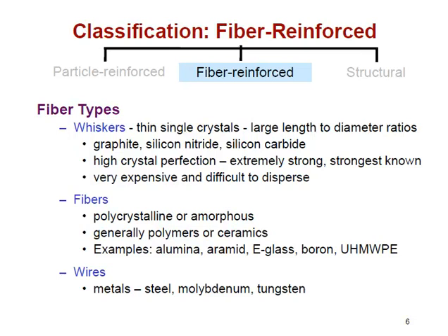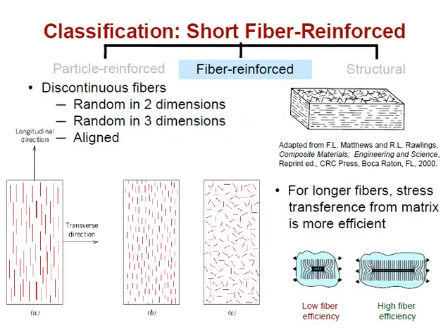This is definitely the case for the ultra-high molecular weight, high modulus polyethylene fibers, and also for most carbon fibers. Obviously, in the case of ceramics, we can get polycrystalline. We're not going to have chain alignment since they're networks, and they will, though, get their strength from the fact that they are covalently bonded, and the fact that, despite the fact that they are ceramics, because they are so thin, they are in plane stress, so that defeats some of the fracture toughness limitations. Metal wires are used less commonly than fiber composites, but would have a role in things like reinforced concrete, a few selected high temperature applications.